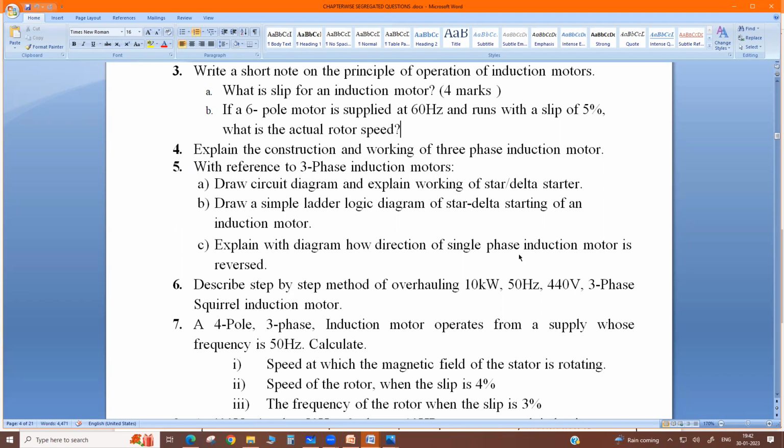Okay. If you reverse the polarity at the supply terminal, phase and neutral, the motor will run in the same direction, no change. Only one winding we have to reverse. So generally we prefer the starting auxiliary winding because the capacitor is connected there, okay? Correct.